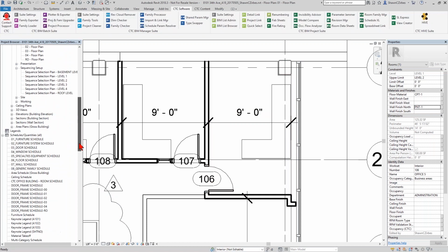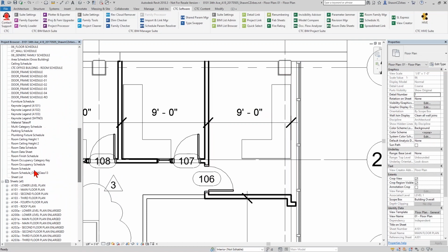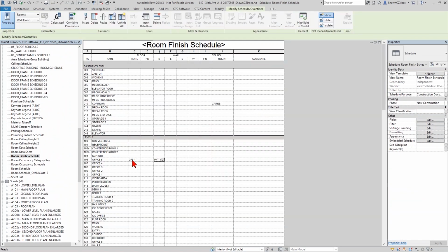So then I started to get a little disillusioned with Revit. And this is why. If I take this information here and I go Control C and I arrow down and Control V, right? I want the next office to be exactly the same. Well, now I got a problem because I can't copy paste a row of information in a Revit schedule. I can't autofill. I can't just arrow over a cell and go copy, paste, paste, paste. It doesn't work that way. You have to type those things out.